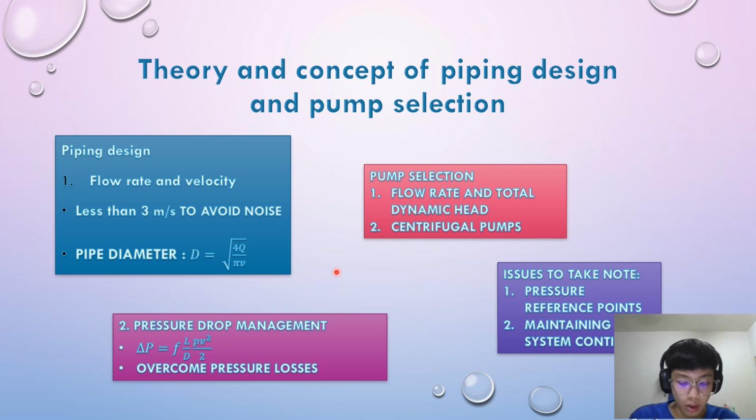head. And an issue to take note of: to avoid isolated sections when using fixed pressure grade or other similar components, ensure every section has a pressure reference point, such as a tank or pressure boundary. Setting appropriate inflow and outflow demand also helps maintain continuity in the system.